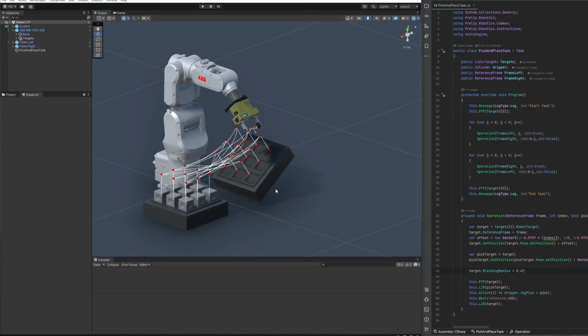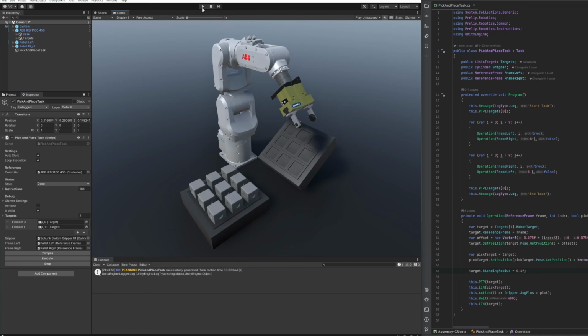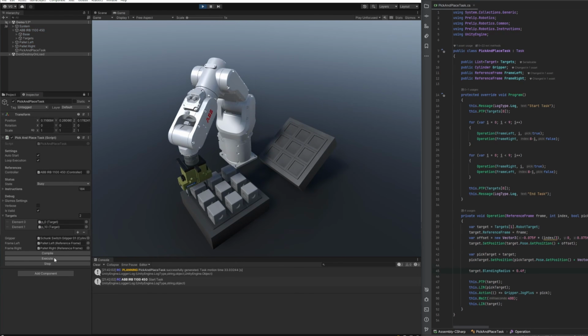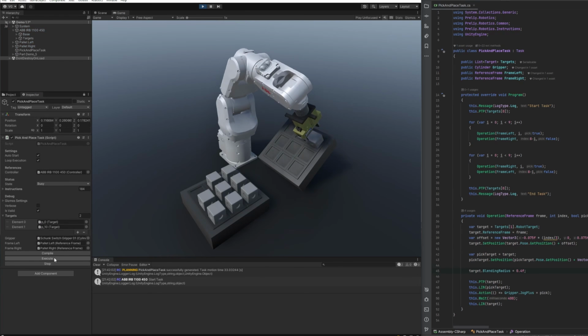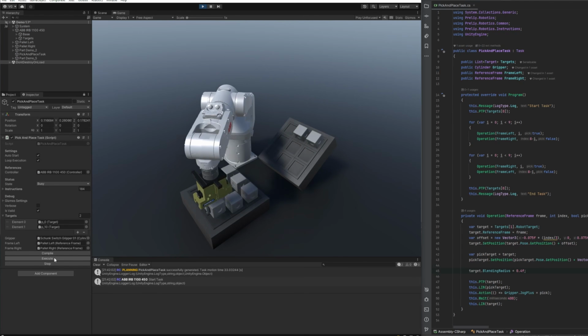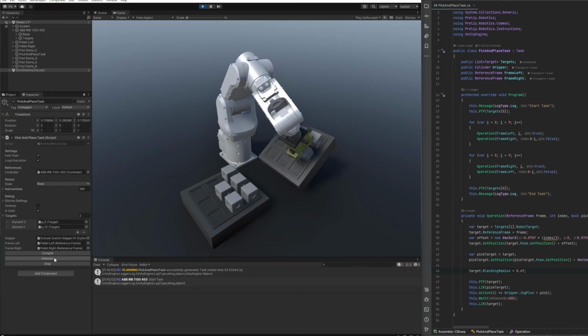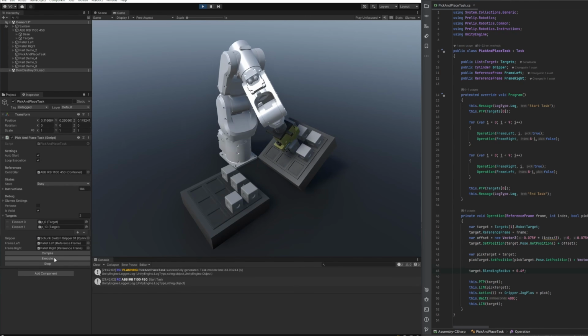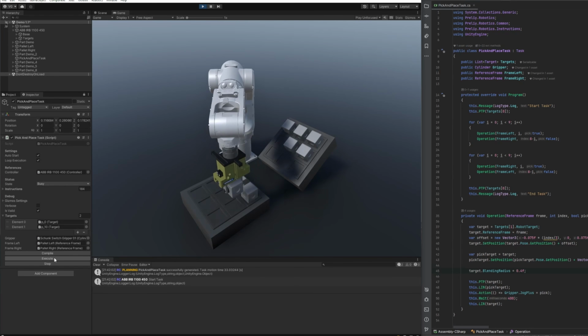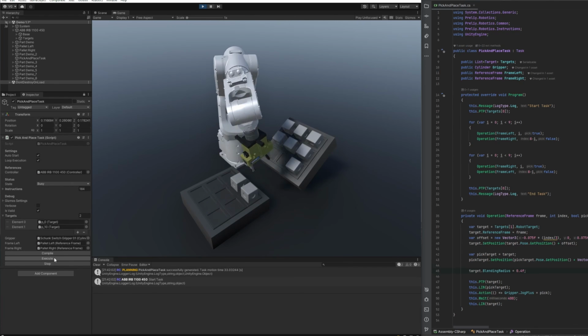When I compile the program, the movement time is now about 33 seconds. You can also see the changes in the trajectory. Now the movement of the robot from the input point to the target position looks smooth. Such blending is the most popular optimization technique in motion planning. In this case, we were able to save 16 seconds, which is about 30% of the total movement time.